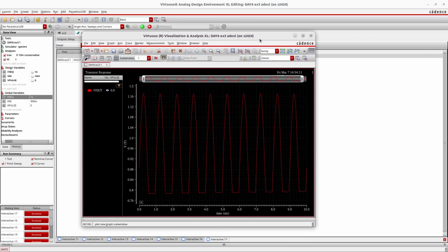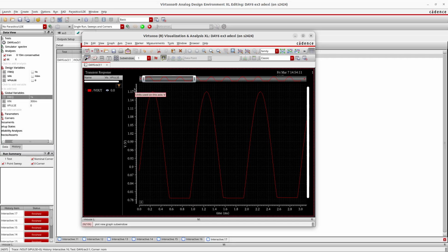And then what we have is as we expected. It is not enough. We needed at least 60 microamps, and the fact that we have only 20 microamps in this current source results in the lower part of the signal being clipped. Yeah, so it just managed to amplify it at around this level, and then it is just clipped.